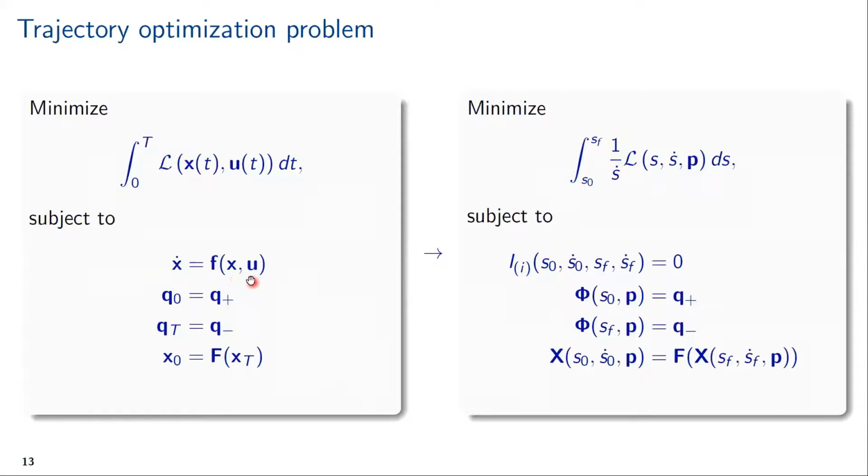So the dynamic constraint may now be written in terms of these integrals of the reduced dynamics. In a sense, if you have five degrees of underactuation, you should not do this, because then you should have a series of discrete sampling points along it, as even though two integrals for different reduced dynamics might both go to 0, there's no guarantee that they will correspond to the same solution. But if you have, say, one degree of underactuation, then you will have one integral, and then it's enough to just check this integral over the given period.